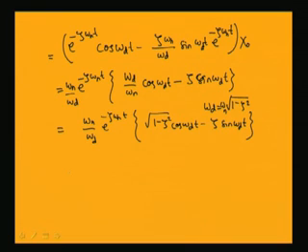So, you can think of zeta equal to cos phi, and this becomes sin phi. If zeta is cos phi, for an underdamped system zeta is less than 1. So zeta can be taken as cos phi, and square root of 1 minus zeta square can be taken as sin phi. So this equation becomes sin phi into cos omega d t minus cos phi into sin omega d t.